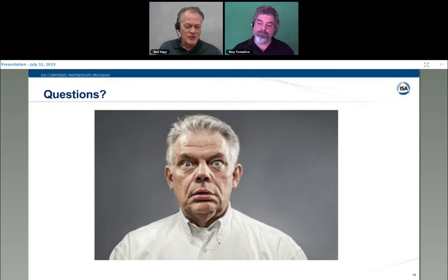Right. And then there's also the system. I mean, the systems today, the transmitters today, can make really good decisions. So if one RTD is bad, you've got the backup there. So it's pretty cool stuff. So in that case, you can do your loop test, but then when you go to analyze a problem within the loop, you're going to have to check both probes at the same time. Maybe you could have a dry block with two holes where you could drop the probes in at the same time and check them.